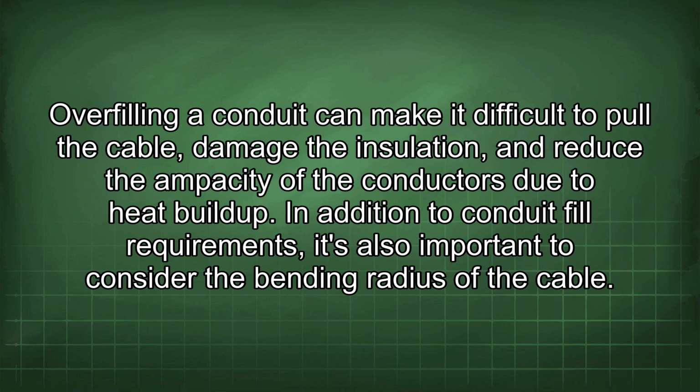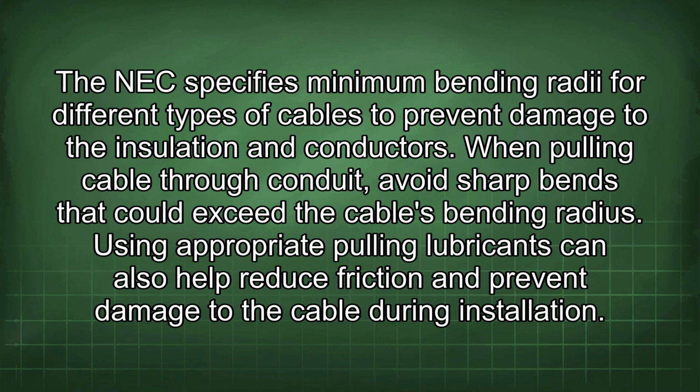In addition to conduit fill requirements, it's also important to consider the bending radius of the cable. The NEC specifies minimum bending radii for different types of cables to prevent damage to the insulation and conductors. When pulling cable through conduit, avoid sharp bends that could exceed the cable's bending radius. Using appropriate pulling lubricants can also help reduce friction and prevent damage to the cable during installation.